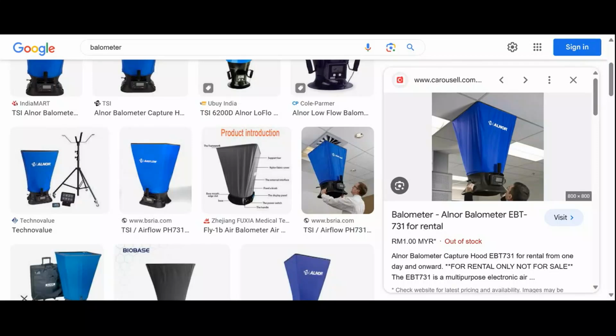Second thing, you can't use these systems for lower applications. If you have 20 TR, 25 TR, you can't use a system like AHU and chillers. It costs more there. It depends on that.